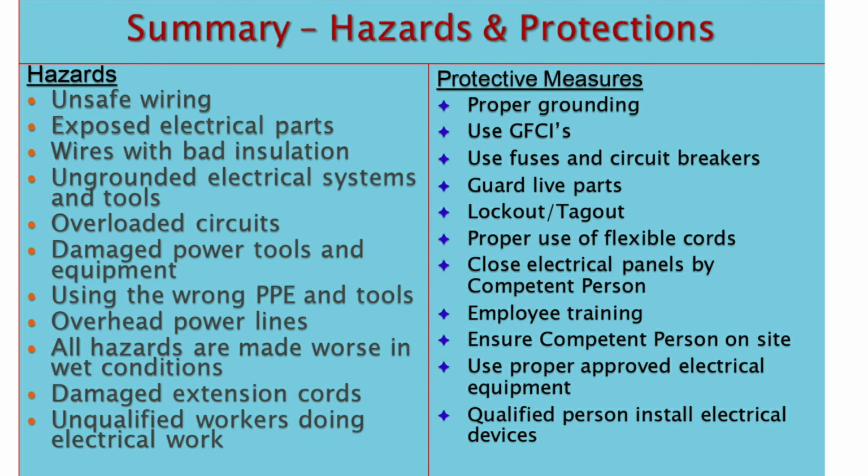live parts, lockout and tagout, proper use of flexible cords, close electrical panels by a competent person, employee training, ensure a competent person on site, use proper approved electrical equipment, and a qualified person installs electrical devices.